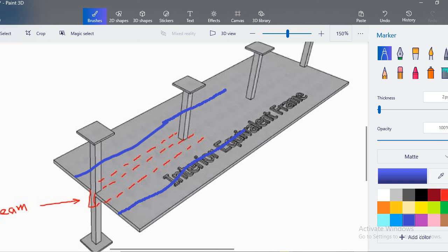Now in a column strip, we have a beam and we have a slab. This is very important. Now the 93% moment, let's say 0.93 of 34. Now how much will it give us? Let me calculate it: 0.93 times 34 gives me 31.62 kip-feet. Now this much moment will be here.